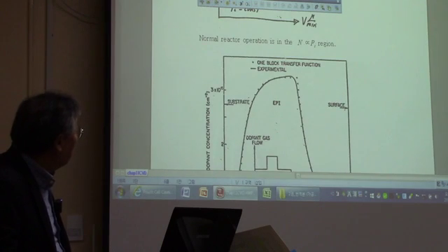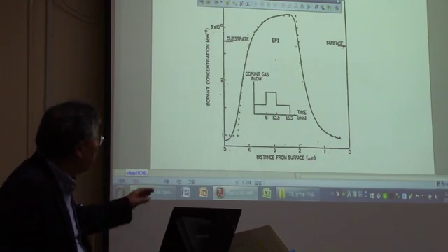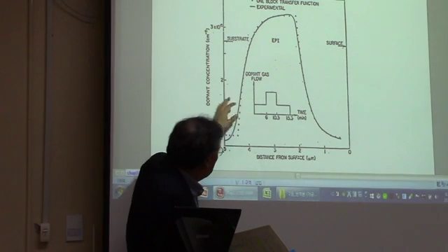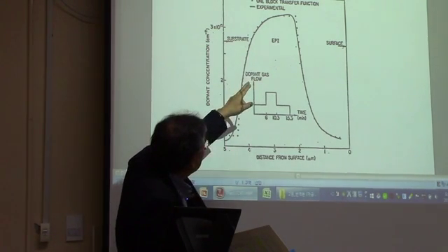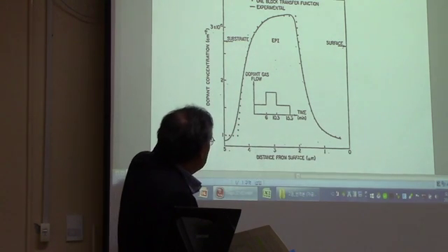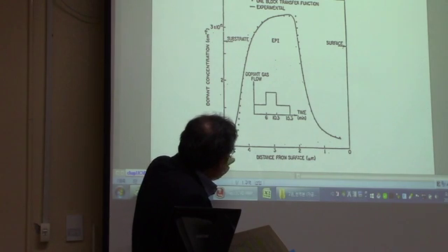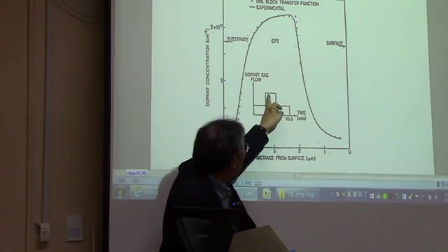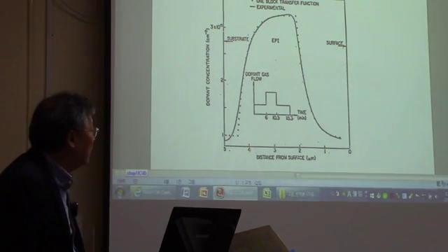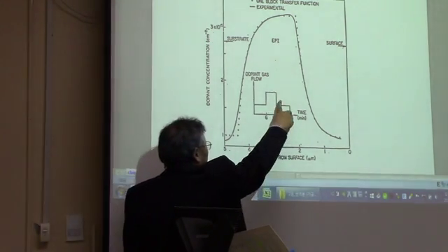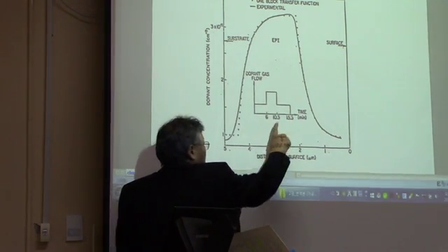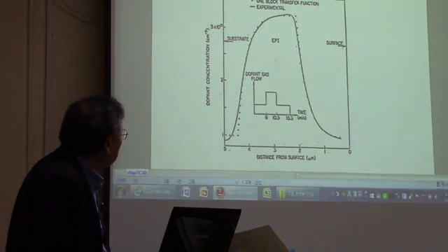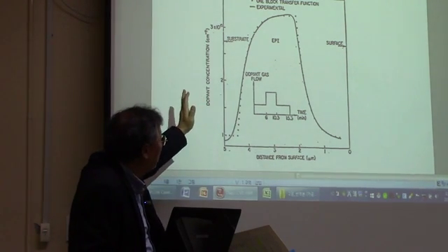Okay, and this is interesting. I think it's an experimental result and the computer simulation. And you see, you open the dopant gas at this time, and then for some 4 minutes or so you keep the dopant gas flowing, and then cut it off after 4 minutes. And then this is the resultant dopant concentration in the epitaxial layer.